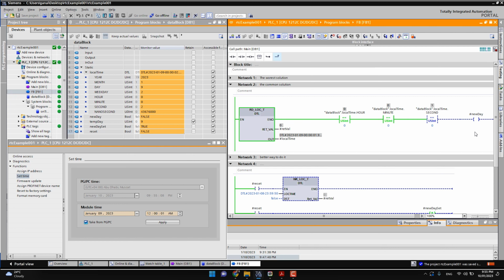And now as you see, we have the trigger. And normally we just add one pulse here in the output because we need one cycle rather than 1 full second of duration for this trigger. The only issue with this approach is, as we mentioned earlier, if you're running on a generator or you missed the 0 clock, then we will keep doing the calculations waiting for the 0 clock. And this is happening in several sites. I see all the calculations are zeros because normally the plant is running on a generator and it is off at night. So the PLC will never see this 0 clock.